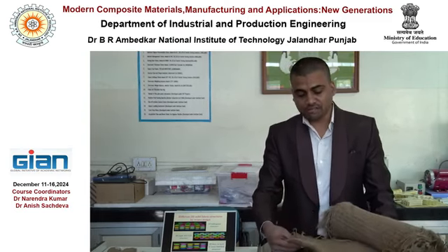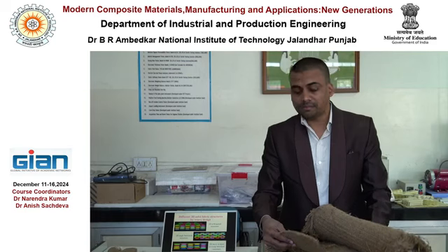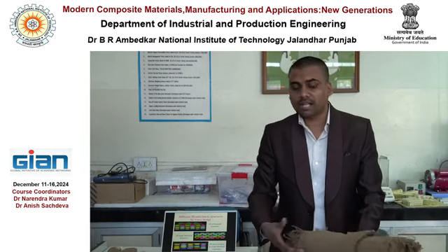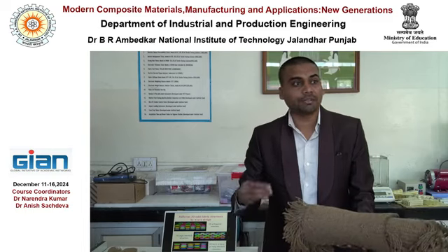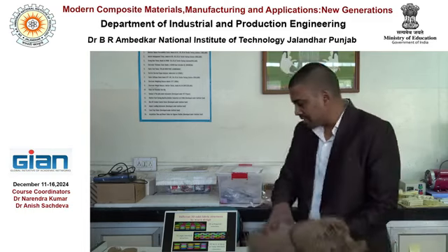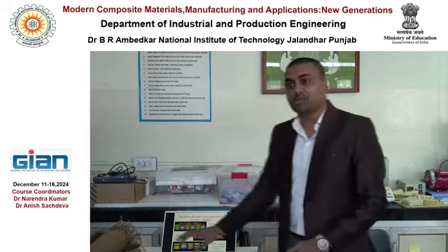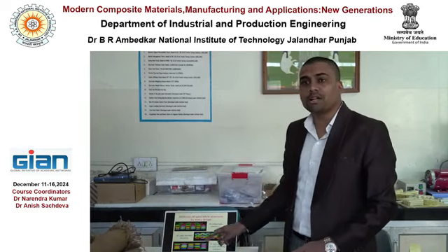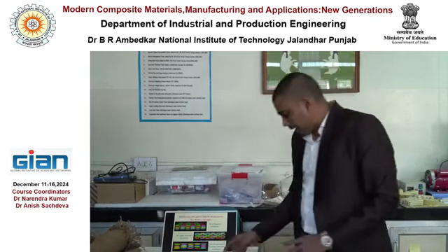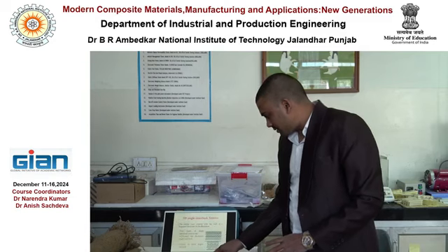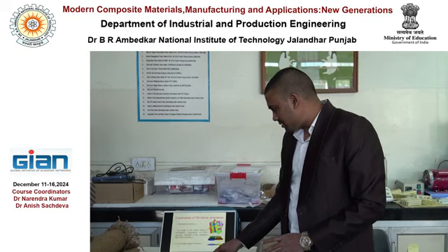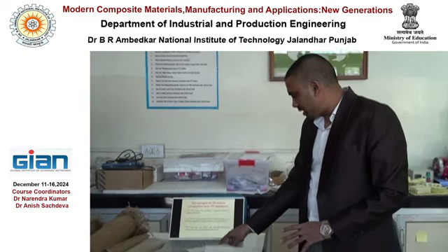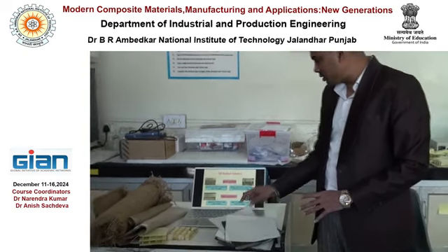This structure is made with the jute. If you make it with the carbon or glass, it will become more stiffer. And bending this particular structure will become very, very difficult. Right. So therefore, in that case, we have to use angle interlock or warp interlock type of a structure. And so we have discussed the limitations of these particular structures also.